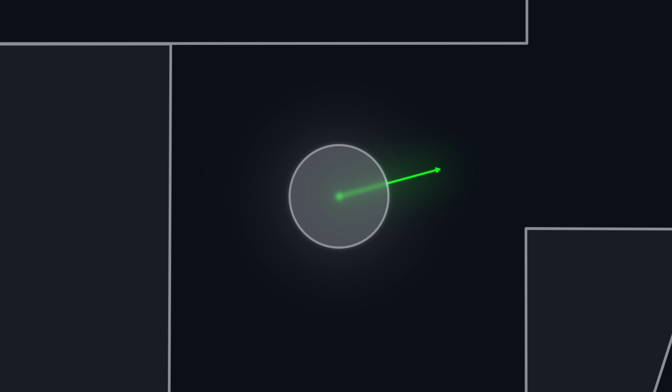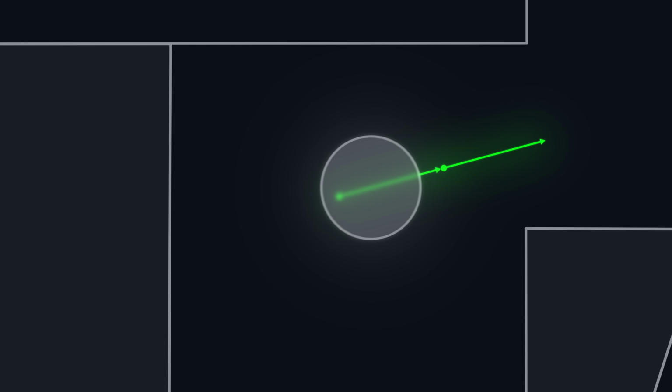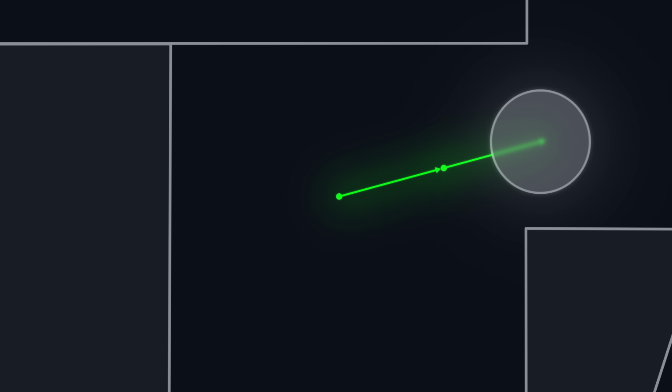A real vacuum has wheels that allow it to rotate and move forward. We'll describe this in our model using mathematical operations. Let's start by looking at how our robot could move forward by, say, 2 units. For this, we'll need the directional vector. Movement in the Euclidean space can be described as vector addition. We simply add twice the directional vector to our agent's position, which describes a shift of 2 units forward in the direction it's facing.